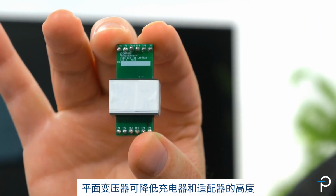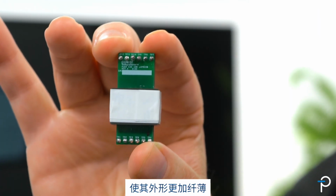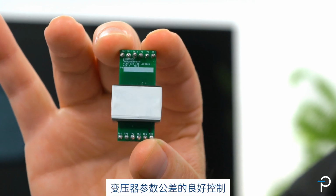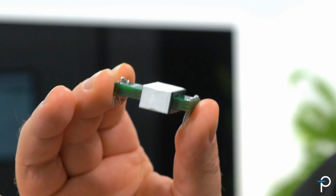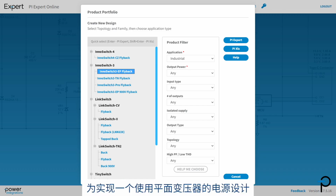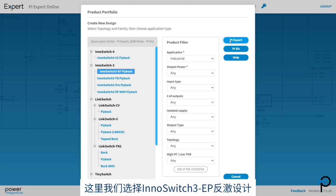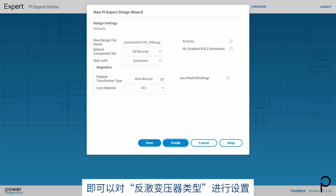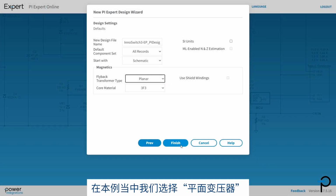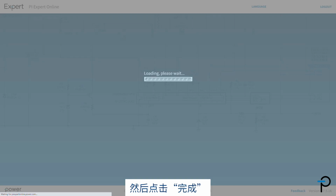Planar transformers enable slimmer profiles for reduced height chargers and adapters, with strong control of tolerancing for reliable and consistent manufacturing. To design a supply solution with a planar transformer, you'll want to create a new design in PI Expert. Let's select InnoSwitch 3 EP Flyback. Now in the Design Settings window, go ahead and select the flyback transformer type, in this case, planar transformer. Then go ahead and finish.